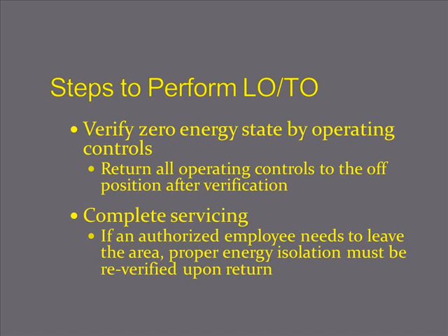Now we need to verify that there is a zero energy state by operating any controls and testing the electrical circuits. Now we're ready to complete our work. If an authorized employee needs to leave the area, proper energy isolation must be re-verified upon return.